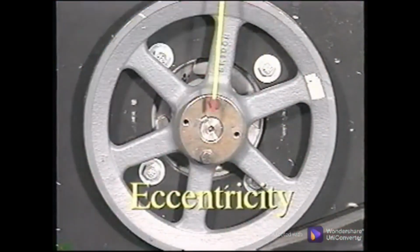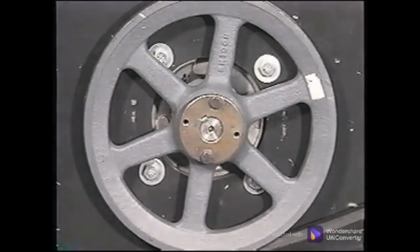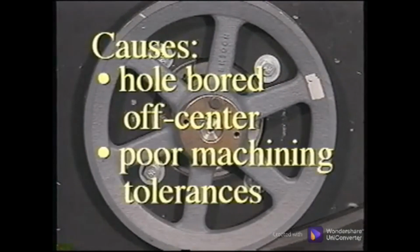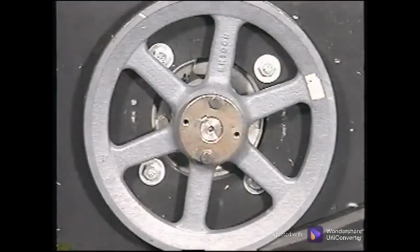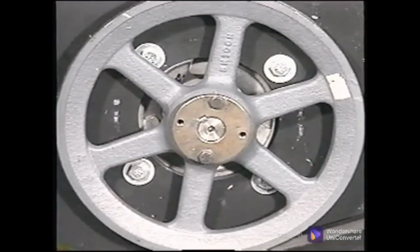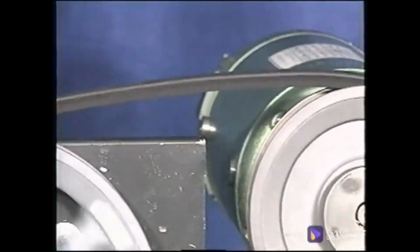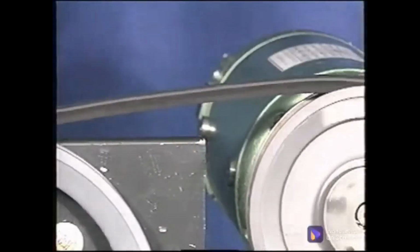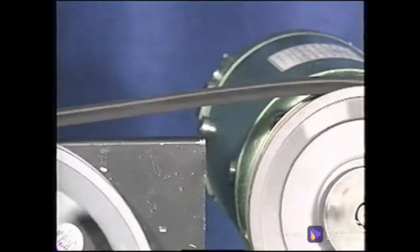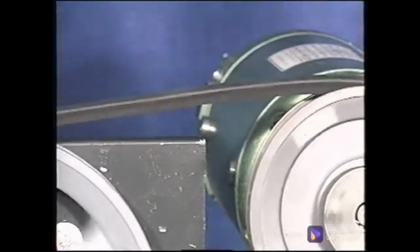Eccentricity is the condition when the center of the sheave is not the center of rotation. It can be caused by the shaft hole being bored off-center or from poor machining tolerances. Whatever the cause, the effect to the belt drive is that one sheave seems to be oblong or egg-shaped. As the shaft turns, the distance the belt travels shortens and lengthens. The belt tension continually cycles from slack to tight, causing the belt to snap each time the tension increases, exciting